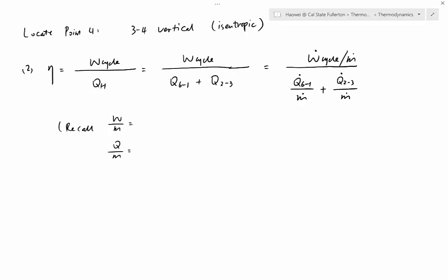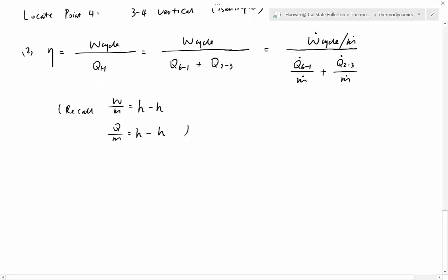The solution is always in the format of the difference of the 2 enthalpies. Enthalpy minus enthalpy. It's always this format. And we always use the bigger enthalpy minus the smaller enthalpy, so the solution will always be positive. If you can memorize this format, everything will just be quick because you won't need to go back to first law again. Okay, so now let's continue.